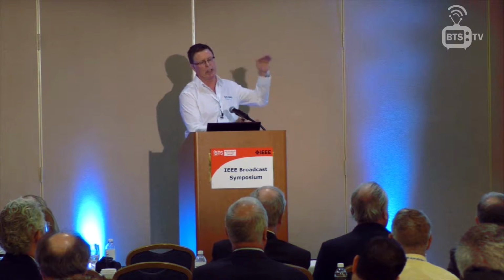We determine what the far field distance is, and that's really a factor of the frequency of operation for that antenna and how much aperture it takes up on the tower. But as a rule of thumb, think of an FM antenna as 450 feet or 150 metres. The VHF antenna might be about 1,200 feet, and a standard large UHF array might be 1,800 feet from the antenna.